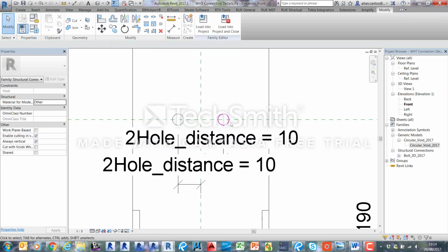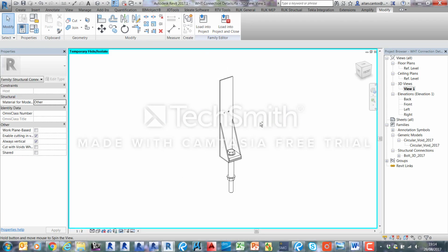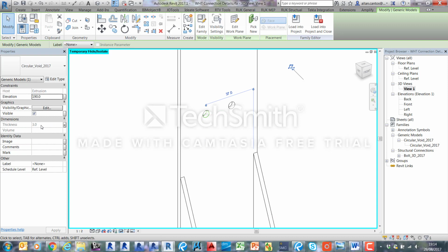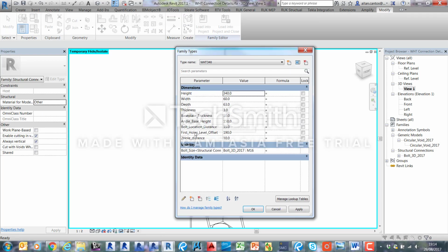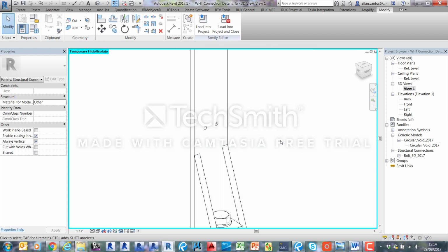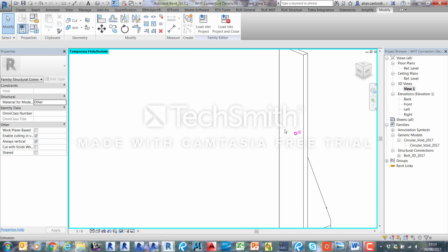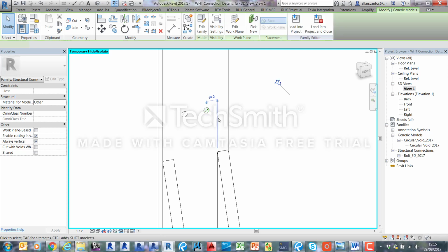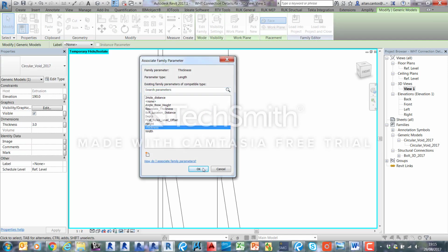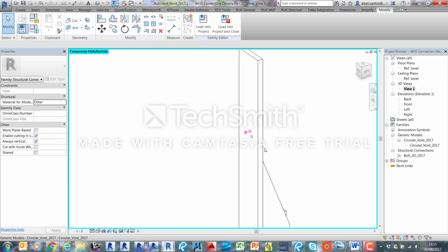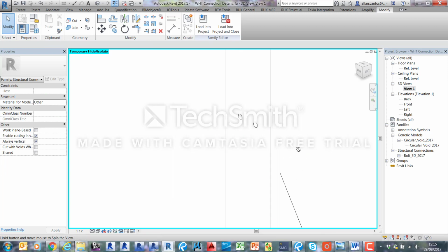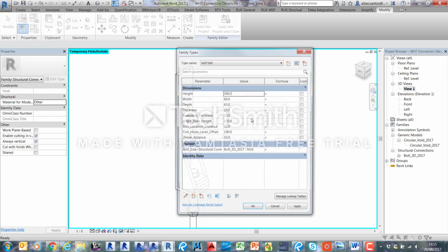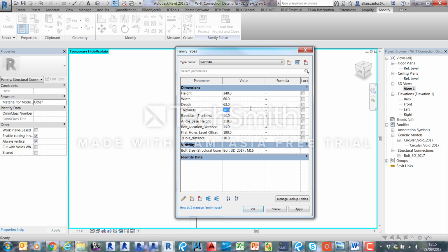Because if we do not do that, I'll show you what will happen. So this one we parameterize the thickness, and this one we just keep it 3. If we update our flange thickness to say 10 mm, if you look behind, the other hole will not penetrate. But if we update that to thickness, we can see the hole punching through that plate. Let's move this back to 3 mm.